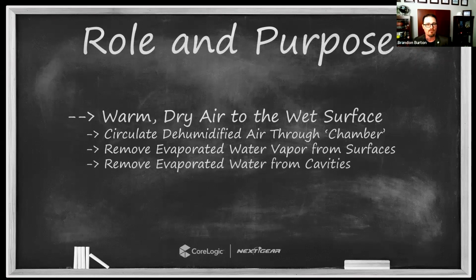The catch here, and the more complicated factor that we just discussed, is that this happens not only on the visible surfaces, this needs to happen on all wet surfaces, whether we're talking about a wall cavity, under a hardwood floor, beneath cabinetry, behind cabinetry, inside of interstitial spaces created by built-ins, anywhere where water has migrated and wet surfaces exist. Okay, so there's a quick look at the role and purpose.